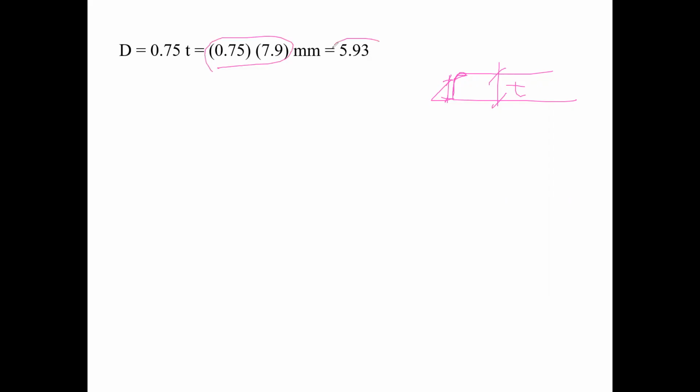Now, guys, 5.963 is a 6 millimeter weld. This is just good practice, it's not a requirement. And I'm pretty sure 0.07 millimeters won't make a difference when you're welding right along that edge there. So therefore I will use a 6 millimeter weld. That would be the maximum one. If I want, I can even go down to 5. It's just that the smaller the weld size, the longer the weld segments.